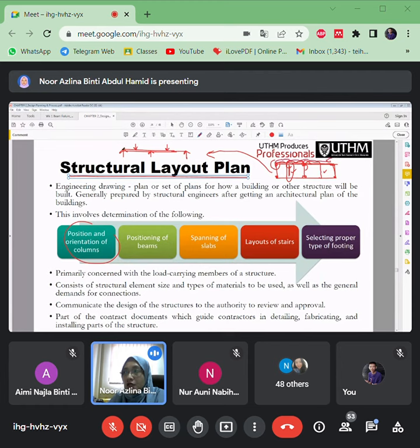So there will be a uniform load along this beam. From here you come out with the estimation of loading from the sketch of the load distribution. So just 3 columns support this beam with the load applied on it: the load from the brick wall, the concrete self weight, the slab, and the point load.